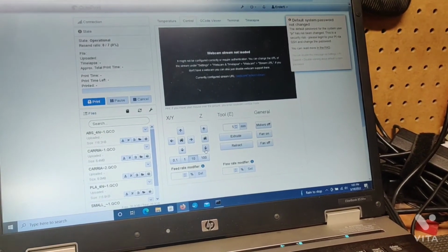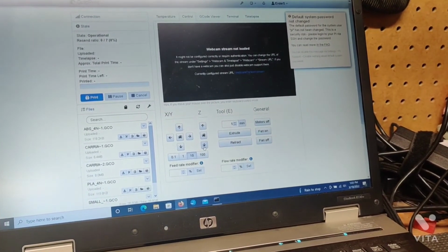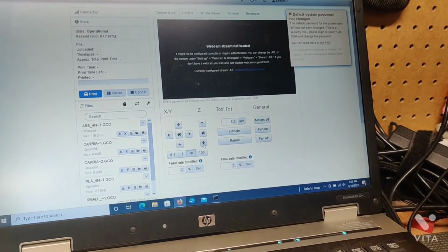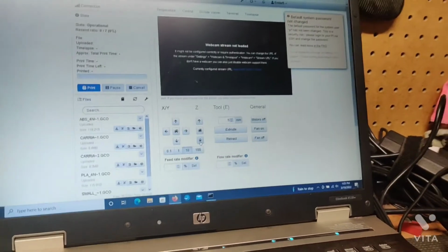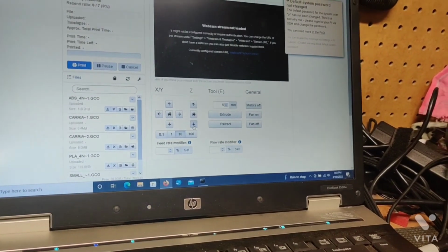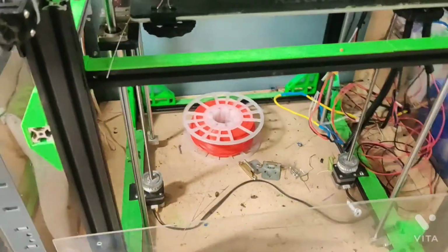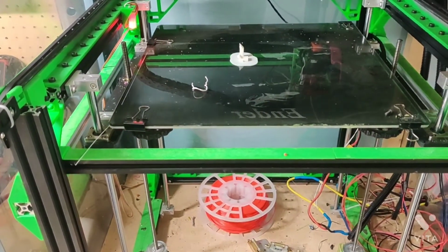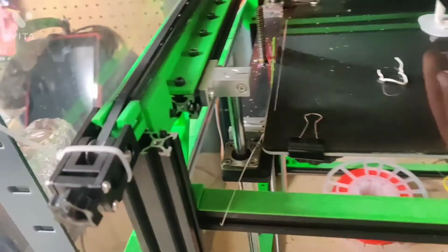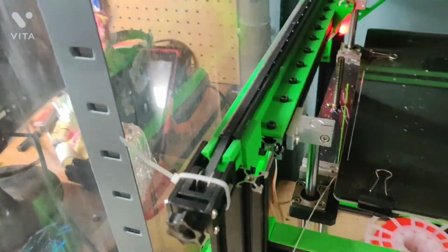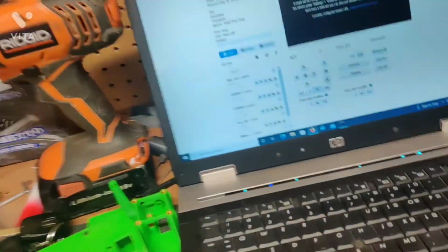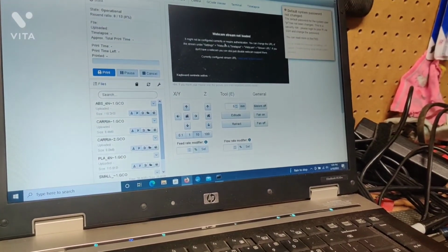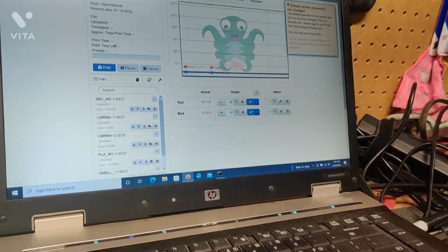Since I reversed my Z-axis, down should be down, and I have it set to 10 millimeters, and we're going to click it and go watch it move. And my bed's going down, so we know that we're connected. Pull these parts off of here. And you can do further tests for your temperature to make sure it's connected.